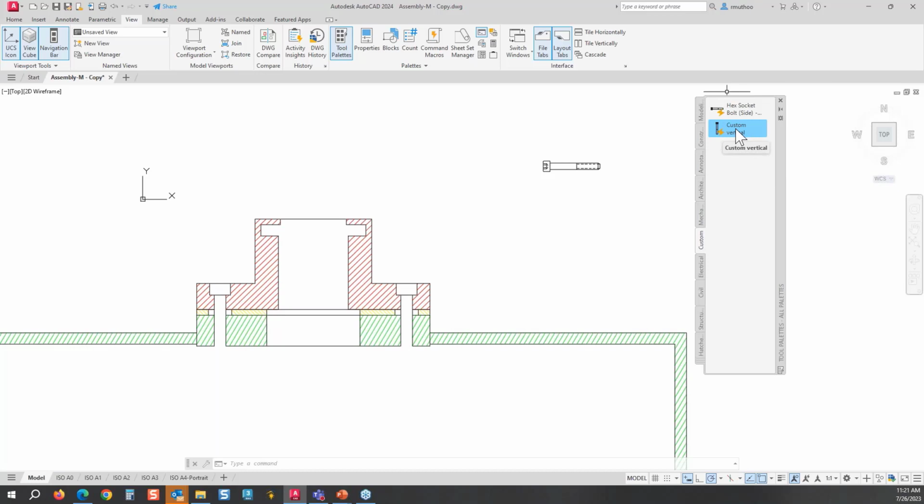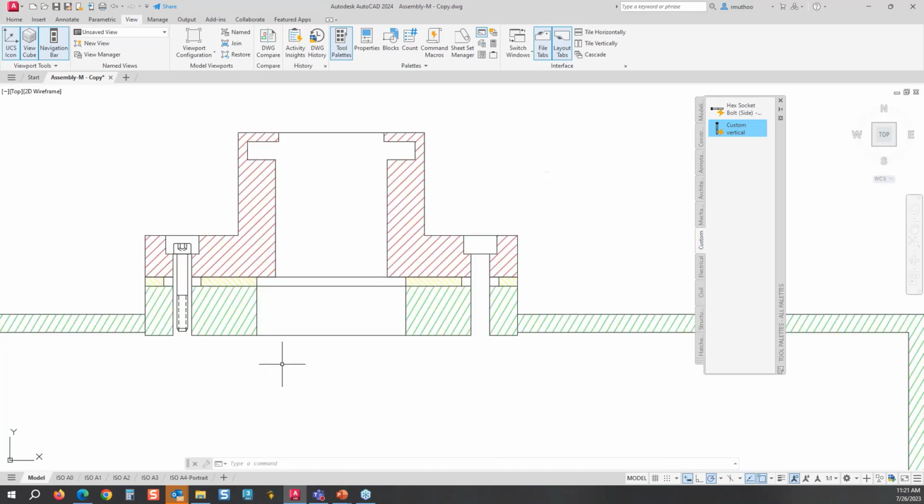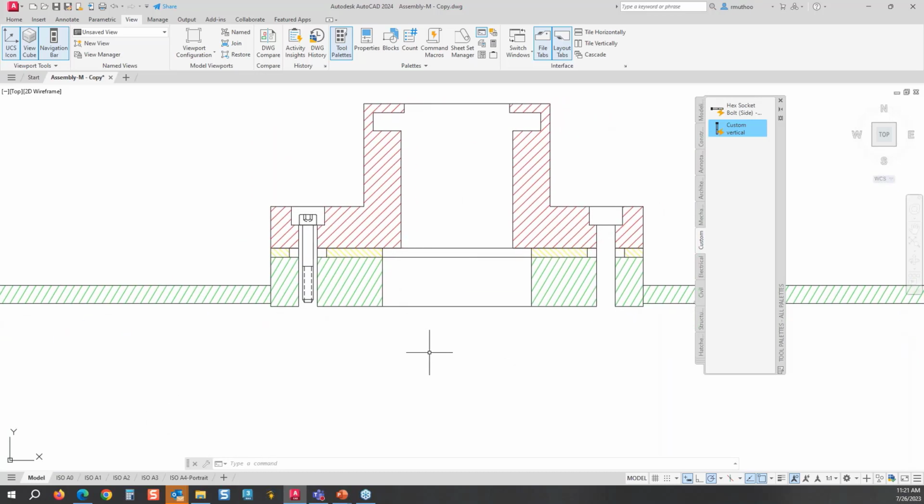So now let's get it, and you can see how easily, and you can do it in any other drawing too. Just place it at the right location, which is the midpoint. Once it is done, you can see it does not fit properly in the socket that has been provided for the bolt. So for that reason, we can first lengthen it. And we know that, being a dynamic block, it already has the lengthen, shorten grip built into it.